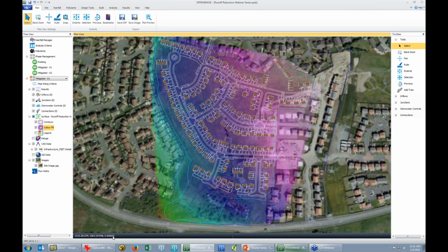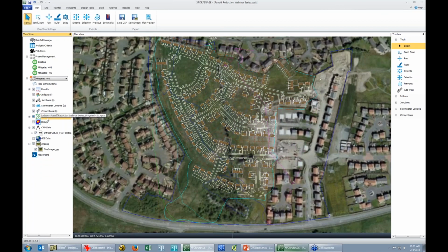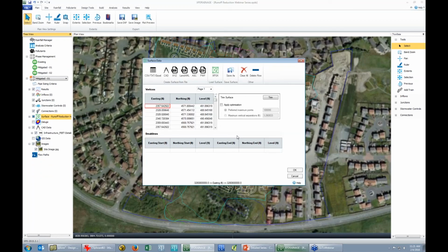Now in the lower left corner of the screen, there's X, Y, and vertical Z value, or Z, depending on where you're tuning in from. So you can see I hover over, here are the elevations on my site. So that's something that I always encourage someone to use. Try perhaps optimizing a surface if it's quite heavy, or trimming it down first and foremost. If you haven't already done that somewhere else, that's a very common task in any project using any software. Well, you can do it right here within our interface. It makes it pretty easy.